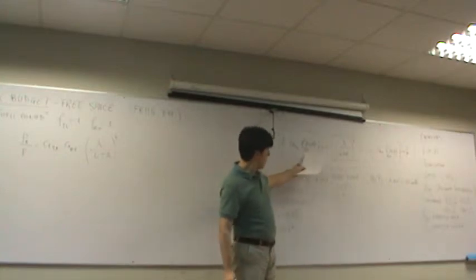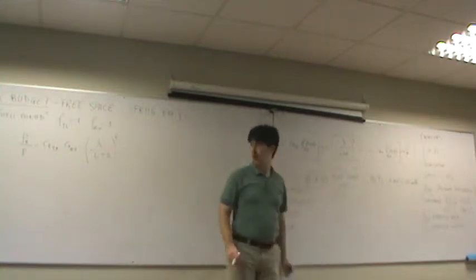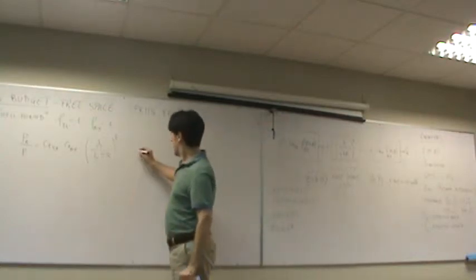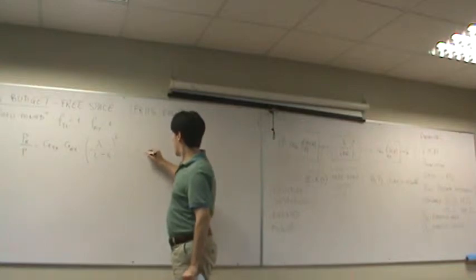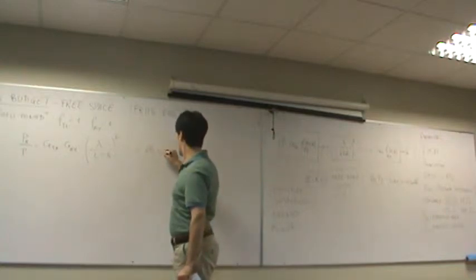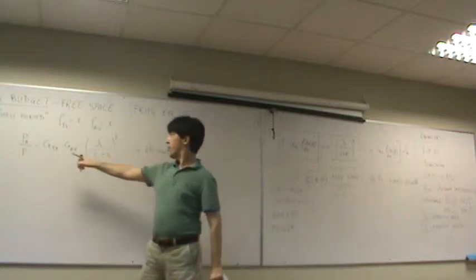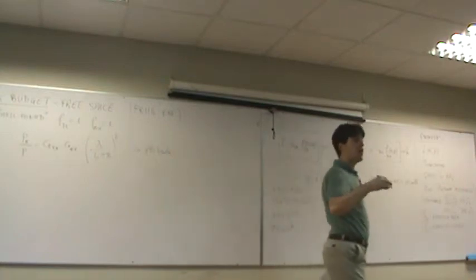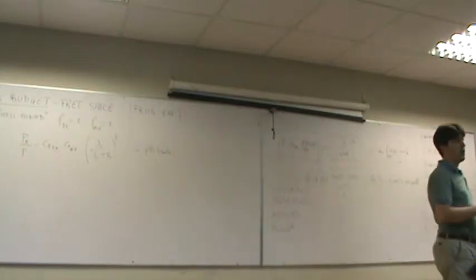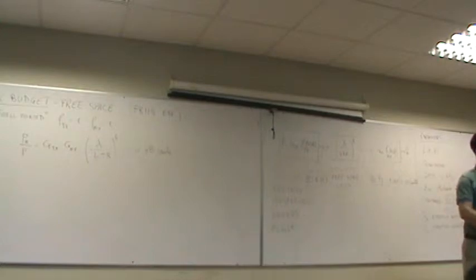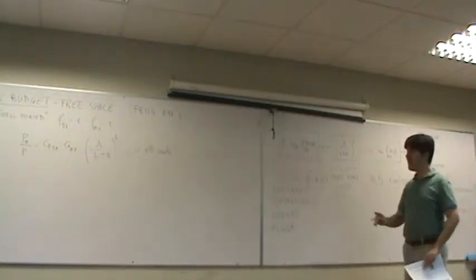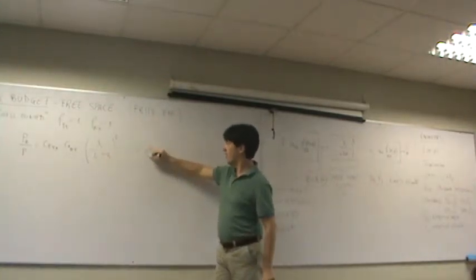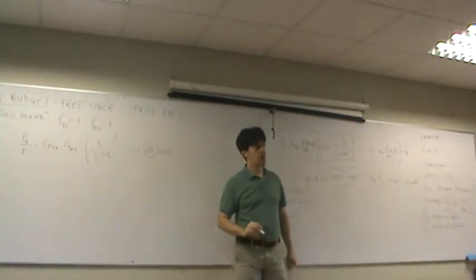I just put this equal to 1 and that other one equal to 1, and since this ratio is a huge number, because the received power is many orders of magnitude smaller than the transmitted power, it's easier to express everything in dB on a logarithmic scale.